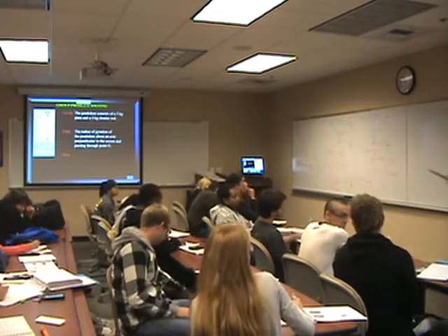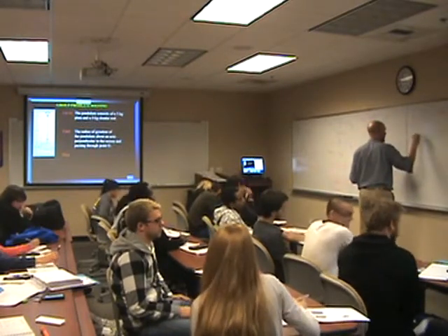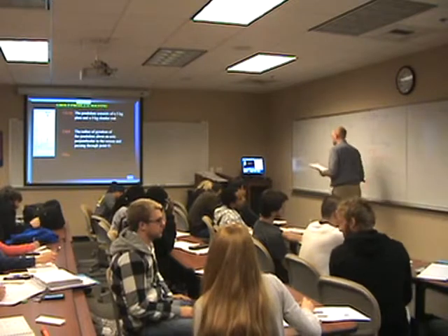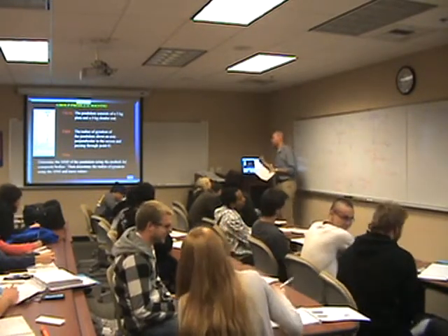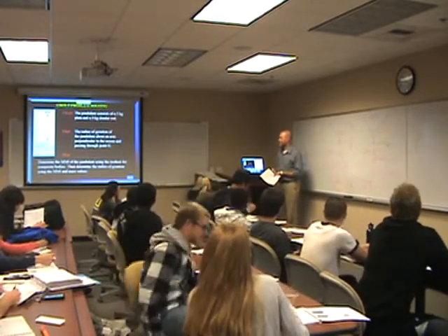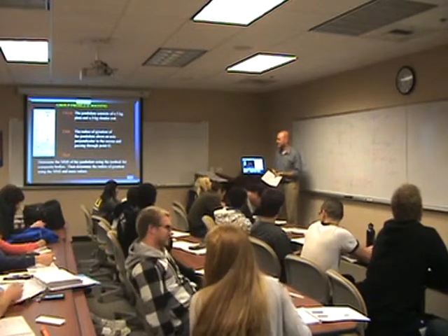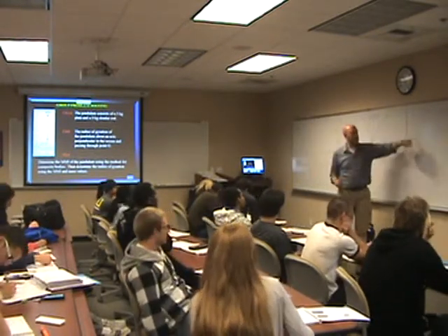So now we need to figure out what IG is. Now we have two components. Our plan is to use the table to find the mass moment of inertia, and we're going to use the parallel axis theorem.